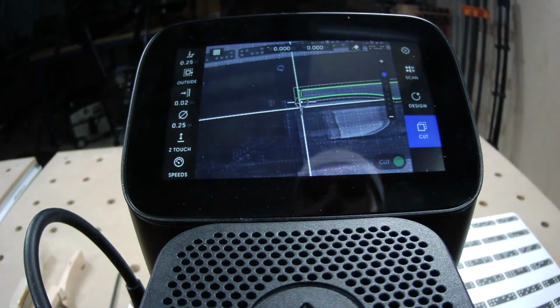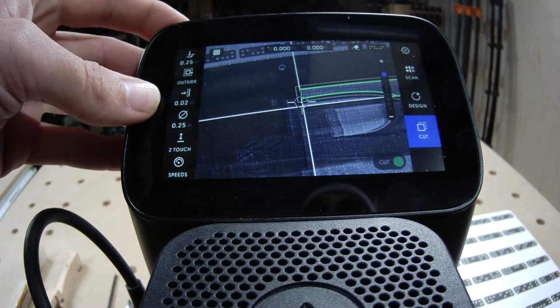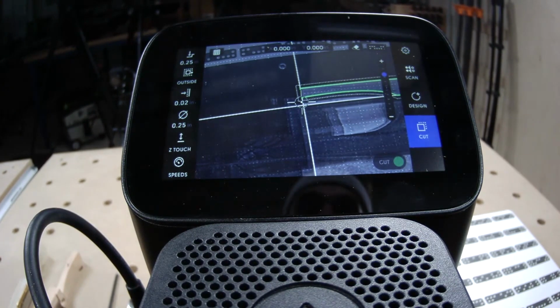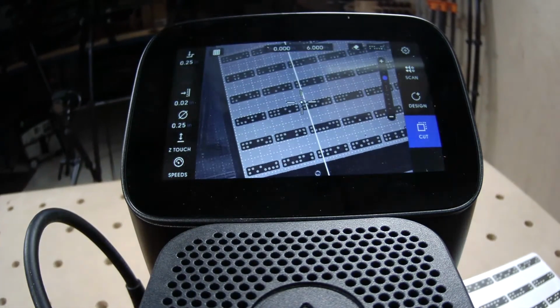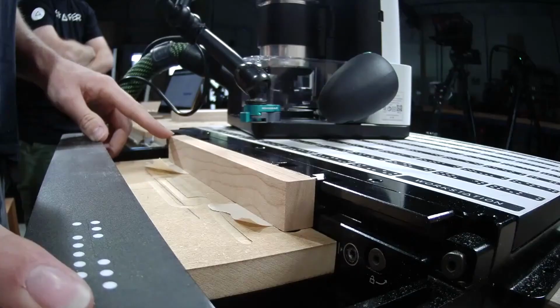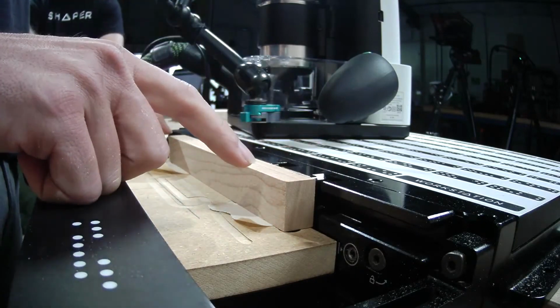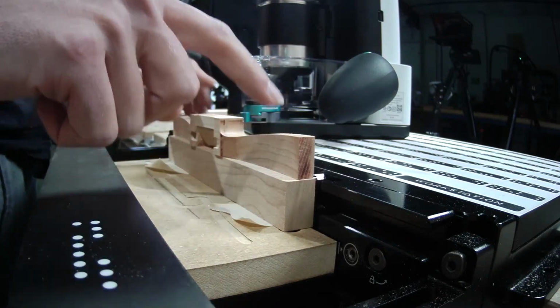Awesome. Okay, let's just get into it. I'm going to do 1/4 inch passes with a 0.02 inch offset, and Sam will walk you through a little more of the details as I get through this. Note, because I have aluminum behind me, if we go over to the workstation cam, Goose, you can see the aluminum's directly behind this, so I have to be very careful about how I'm cutting. Because of this shape, I'm only cutting the front piece.